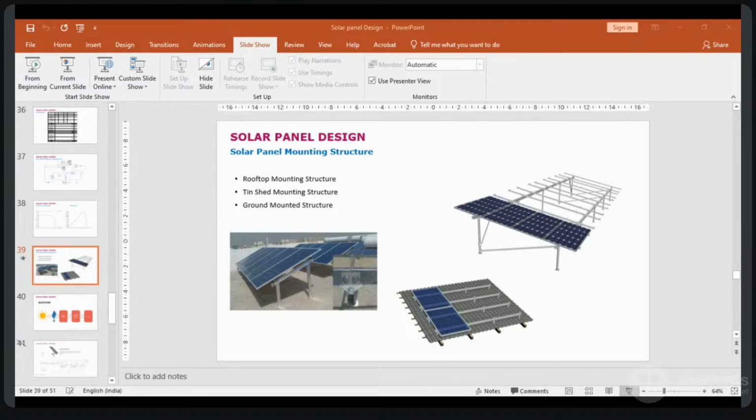Generally in the market, different types of earthing are available. For normal kilowatt, like 5 kilowatt, generally you can dig 3 to 5 feet, that is okay. But for more than 10 or 20 kilowatt, you have to dig a minimum of 8 feet. So minimum 8 feet only, we can do the earthing kit. You know how the earthing is generally done. We generally use a mixture of salt, charcoal, and sand.